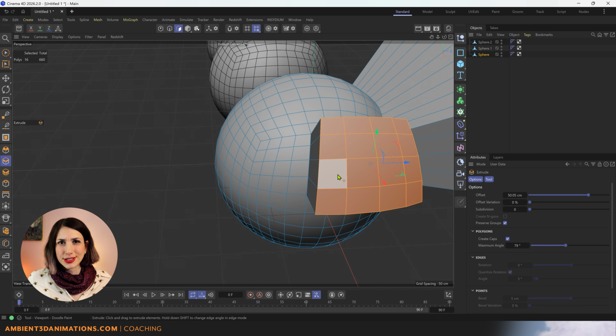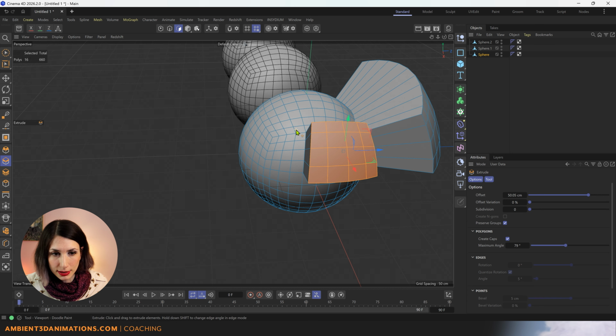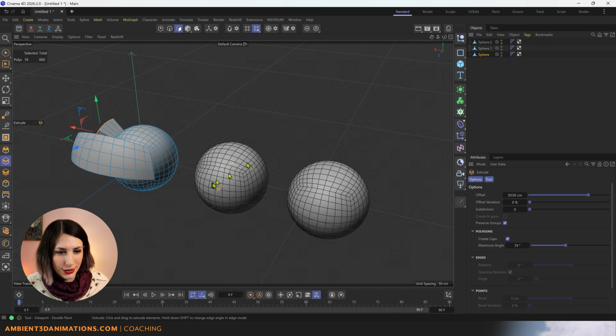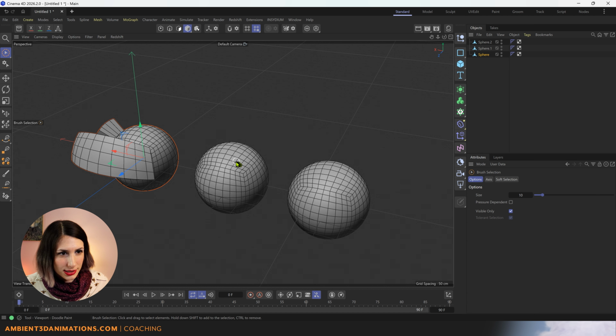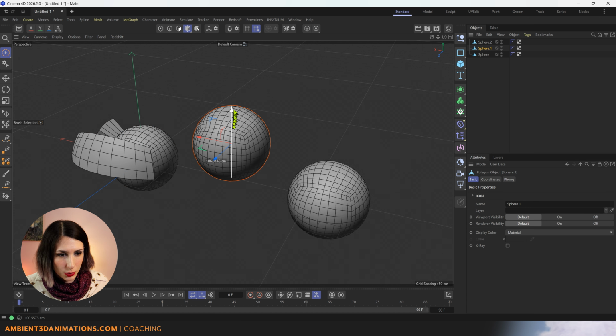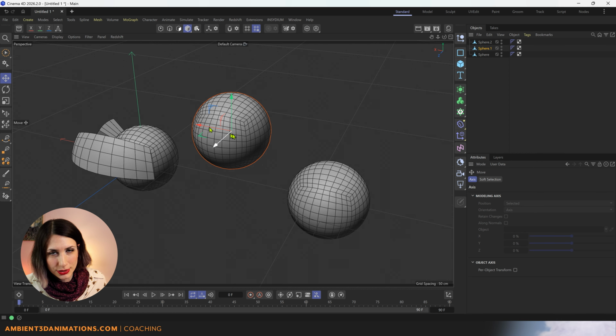What if we want to 3D model using edges? What if we want to extrude our edges? Well, let's talk about that a little bit on our next sphere. So I'm going to move on over here to sphere number 2. I would actually like to go into model mode, hit our selection tool here, click on this, and just move this up. The hotkey for the move controls is E, so if you aren't seeing these arrows here, you just need to hit the E hotkey.